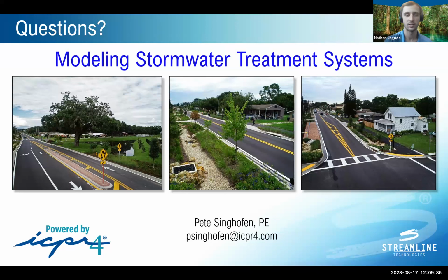With any of these, you have to maintain them. You can't just ignore them. The rain gardens, I went out there a couple of months ago, and they had been in the ground for at least 5 years, and they were looking pretty good. The pervious pavers, and that's not really my expertise, working on the maintenance, look like they could use some vacuuming and some type of maintenance on them.